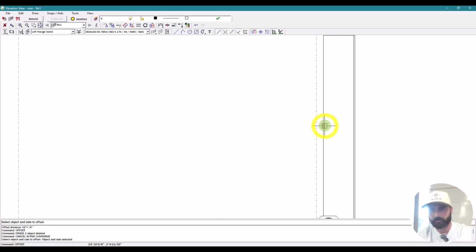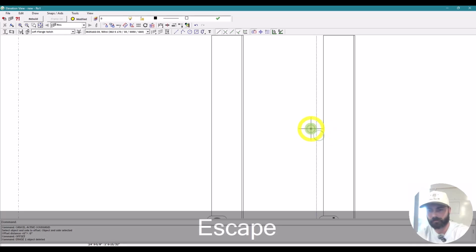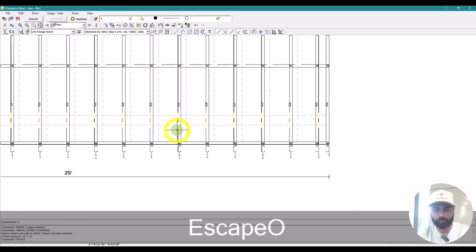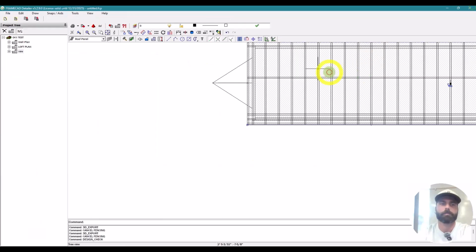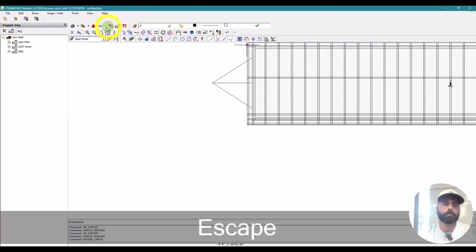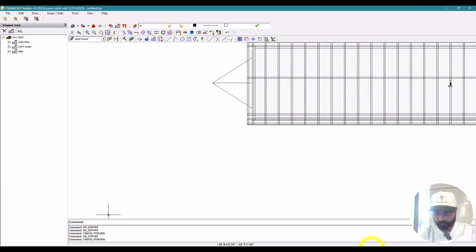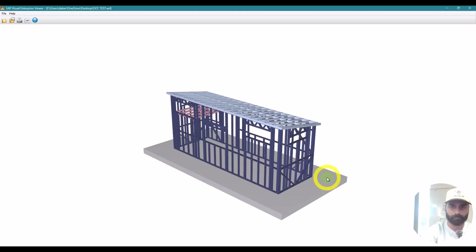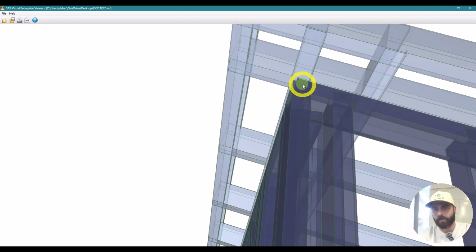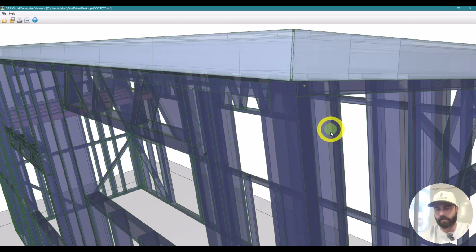There we go. So now we've got deadwood studs on the roof along the interior. The only thing we would still go do is we have that one that's aligned at 14, and then I'd offset this 3 5/8 inches on these two here.